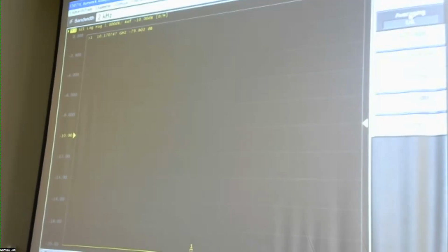So this is the standard signal process. There are some additional things you can do to make the trace look nice, like smoothing and aperture. That's just adding another filter, or equivalently clumping 4-5 frequency points into one point and calling that one number, just called smoothing. But again, these are not super important.